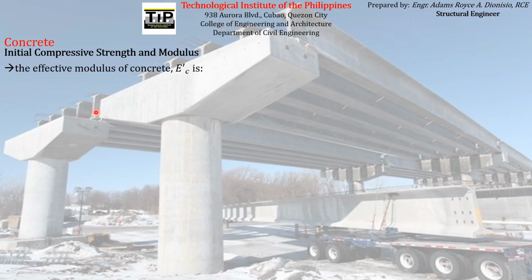If you want to find the effective modulus of concrete, E prime c, the formula is this. Just divide the stress being experienced by the concrete by the elastic strain plus creep strain. May I just recap the elastic strain? This is the strain being experienced by the concrete as you apply the load. It is an immediate strain experienced by any material when a load is applied to it.